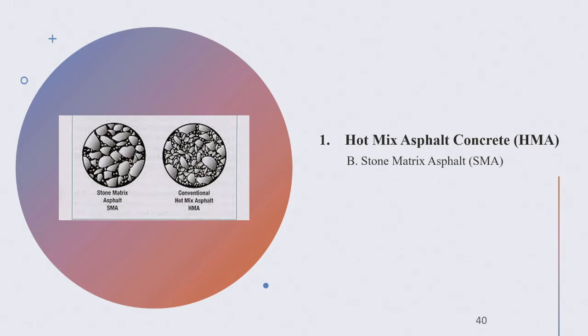And why is that? Because coarse aggregate particles bear on top of each other. So when the vehicle or the tire or any type of pressure is applied on a wearing surface, if you don't have that coarse aggregate, the wearing surface itself is flexible. You would start seeing slight rutting that would expand, and that is top-down rutting. It has nothing to do with bottom-up rutting, right? So having the stone matrix mix, with a higher percentage of coarse aggregate, usually 30 millimeter, you end up with huge bearing force, which is great in fighting rutting.